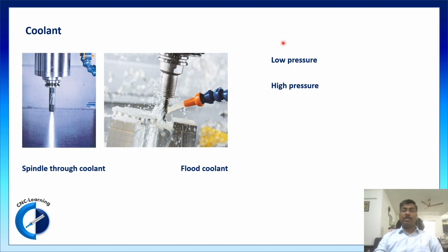Then you need to also look at the pressure requirement for the coolant. A standard machine will come with low pressure coolant, whereas high pressure coolant will always help you to increase the tool life, and it will also help you to evacuate the chip effectively.